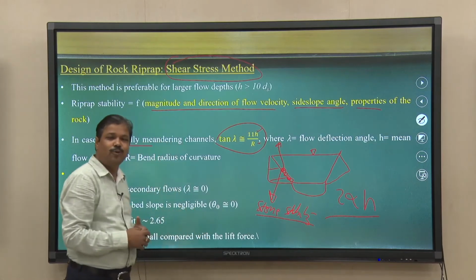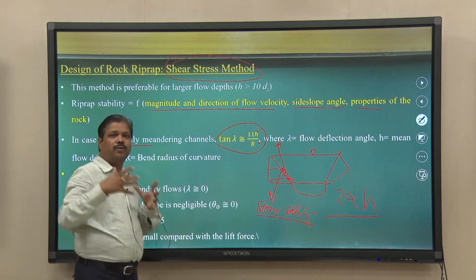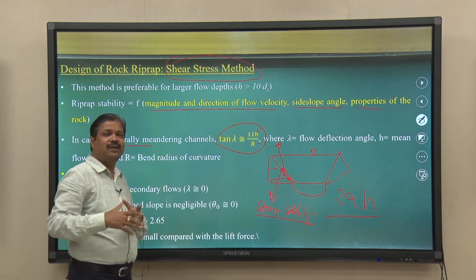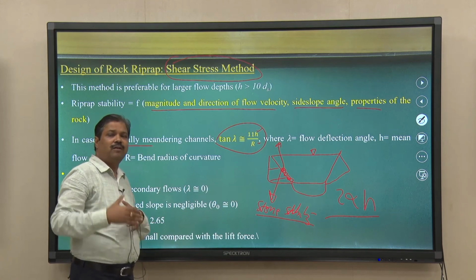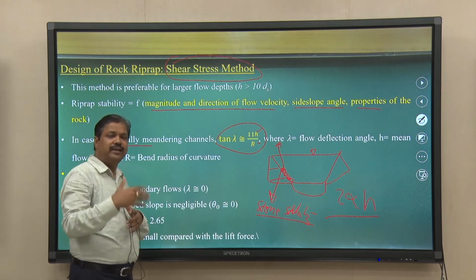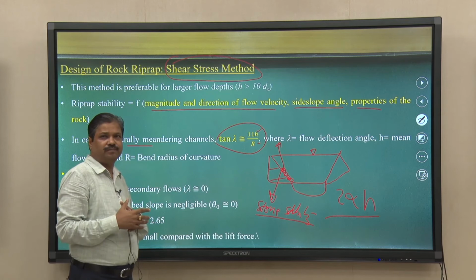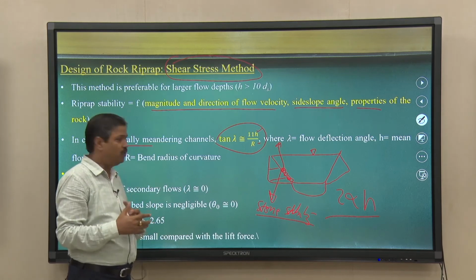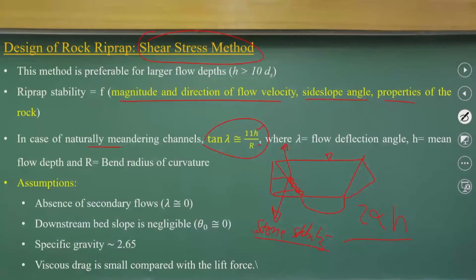We should look at the stones we dump over these rivers during flood situations, whether these stones are stable at those positions. So, we should do stone stability analysis as close to the particle stability analysis we discussed earlier.